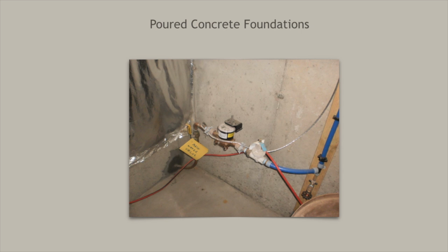There are two areas of concern that can compromise a foundation after being poured: backfill and weather conditions. Backfilling in this type of foundation must be done with care, especially if there is no bracing or lateral support. Too much pressure from the backfill and the wall will crack or, in extreme cases, collapse.